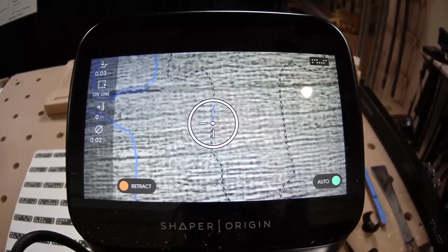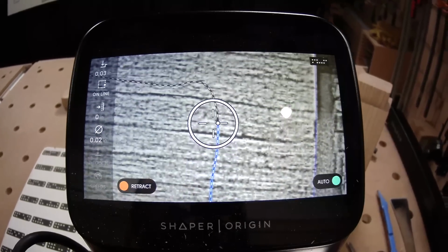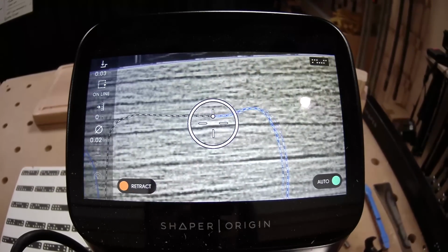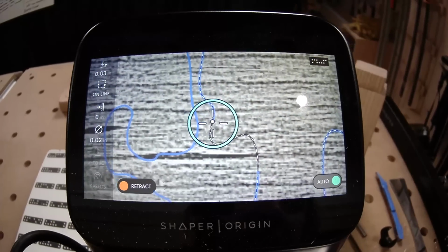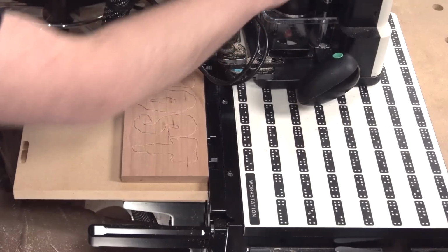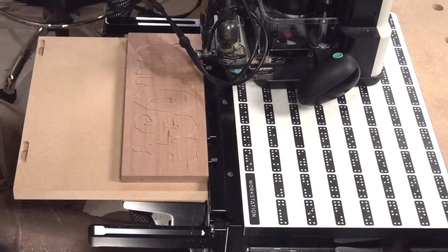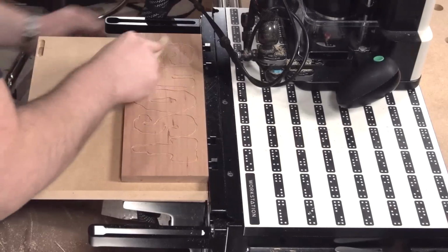A little bit. Add a little friction to the base and the material you're cutting so you don't get any unnecessary slips. Yeah, people ask, how do I reduce the friction in my base? And I would say you don't want to reduce the friction in your base. It really helps you keep things on the line. Yeah, don't ever wax the base. Don't do anything like that. Don't try to lift it up to reduce the pressure. It feels a little funny at first, but you're going to get used to it. The friction is a really good thing. The friction is engineered to give you good quality. And so, like the tape, all the work surfaces on the plate and workstation, those are built for the best friction.